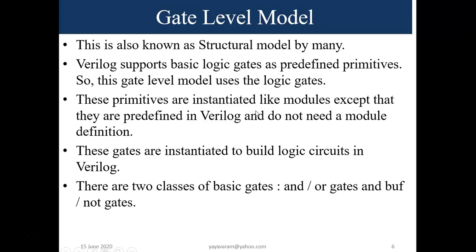These primitives are instantiated like modules, except that they are predefined in Verilog and do not need a module definition. Very important. Another interesting thing is many of the students will have a doubt about what is this instantiation. Normally Verilog engineers will use this word. Instantiation is nothing but calling, invoking. Because as I just now told you, Verilog has many predefined logic gates. They are already there. The only thing that you have to do is instantiate them. That is, you have to use them or invoke them, call them. Simply calling and using them in your program. That is the meaning of instantiation.